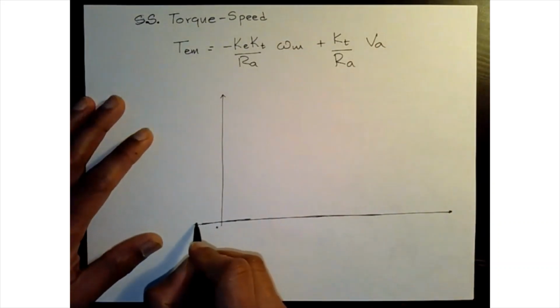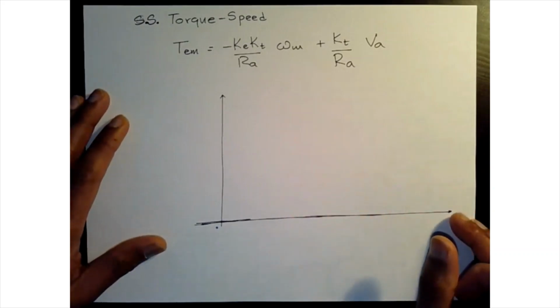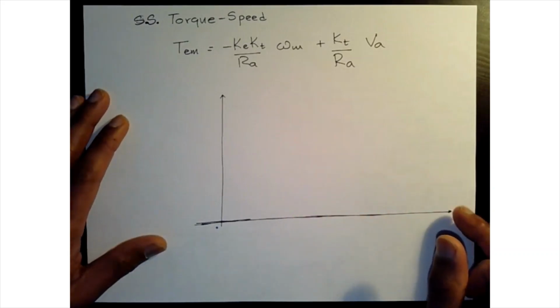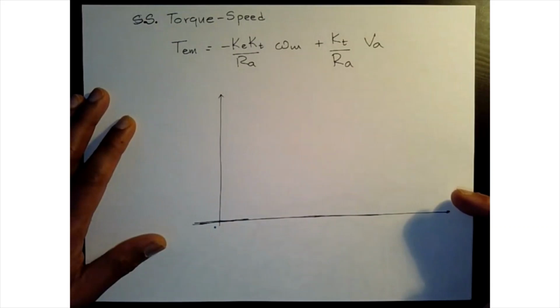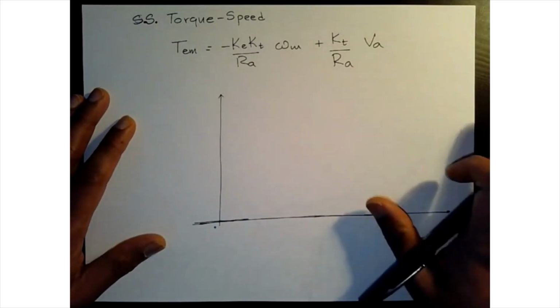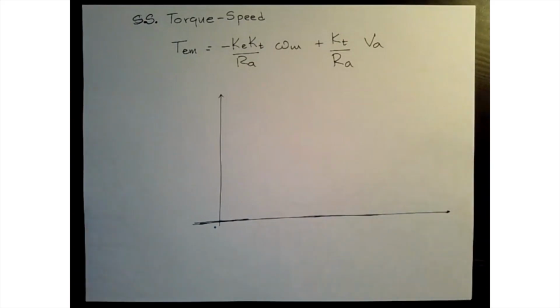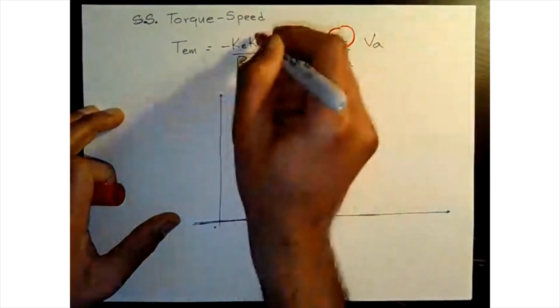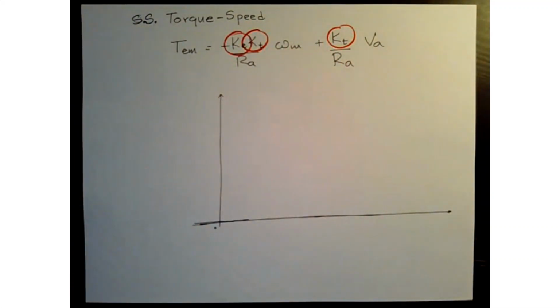That's another advantage of having this capability for AC machines. It will be much clearer and easier to understand rather than jumping directly into AC machine field weakening control. Now we know that with our field winding, we can control this, and this. That's the only parameter that we can control by adjusting our field winding.